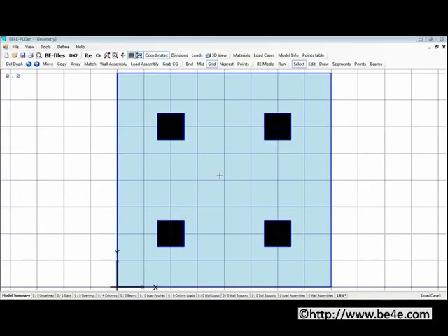To give you an example of a loading element, I'm going to start off with the tutorial 1, simple square slab with the 4 columns. What I'm going to first give as an example is a load patch. A load patch is a load applied on the surface of the slab, for example, a machine. Numerically, the load patch is divided into divisions. To display this, I'll apply a load patch on the surface of the slab we have.